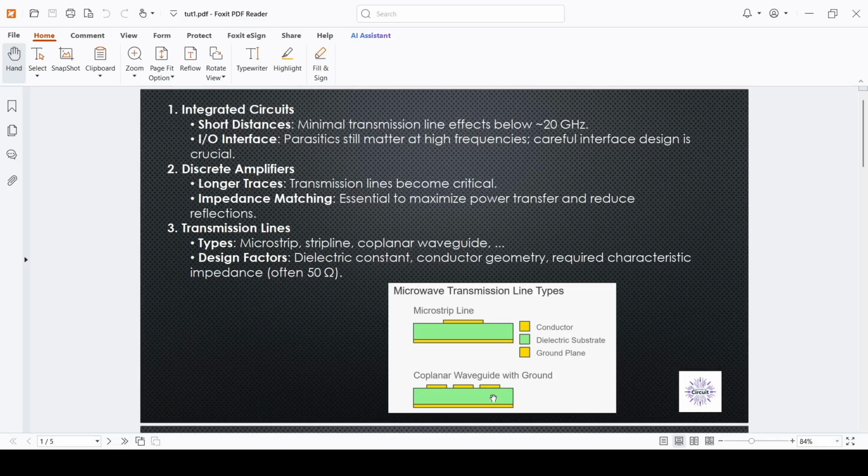But for this design, I found that I can actually use ANSYS Electronics Desktop, a student version of it, which is very useful because with that license I can use HFSS and other circuit simulations to not only accurately design the transmission line, but also simulate the rest of the circuitry.